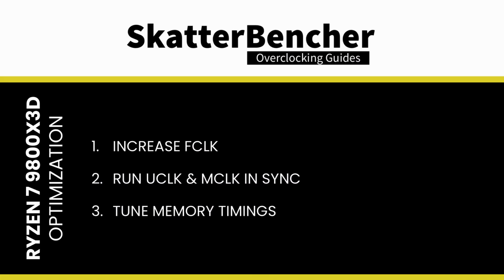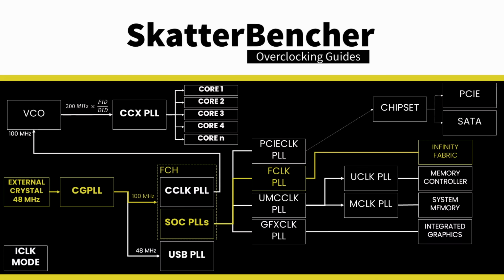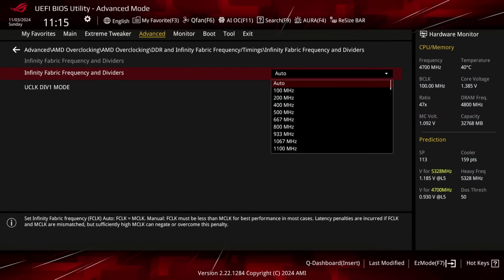There were 3 things I wanted to address with the memory subsystem performance optimization. I want to run the Fclock as high as possible, I want to run the UCLK and MCLK in sync, and I want to tighten up the memory timings. The fabric frequency, or Fclock, is generated by the SoC PLL derived from a 100 MHz reference clock input. The reference clock input is multiplied by the Fclock ratio, which you can configure in the BIOS.